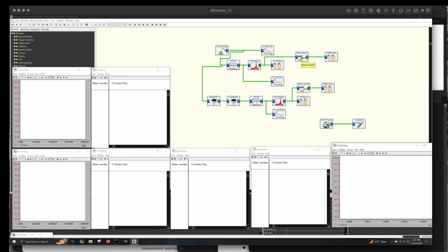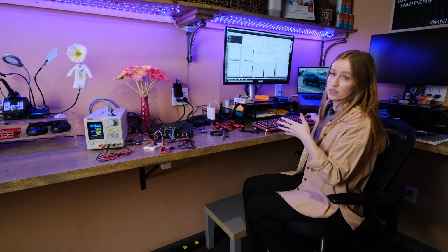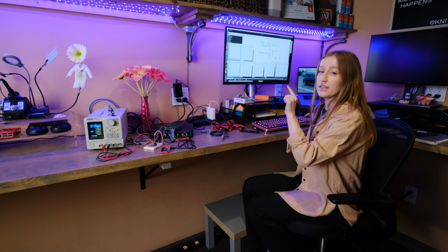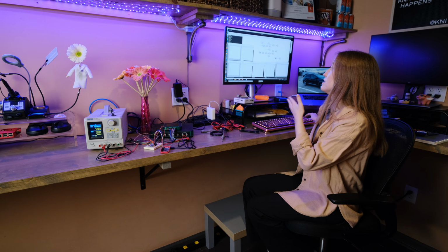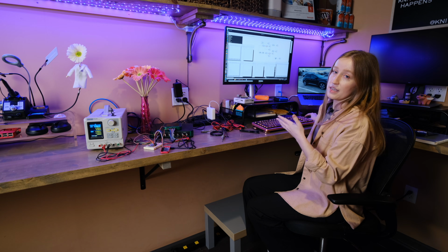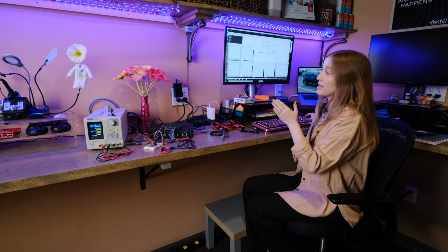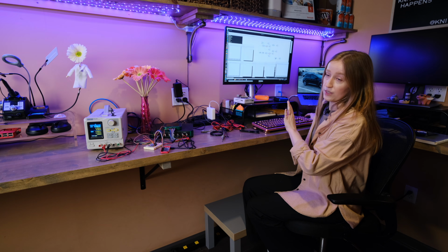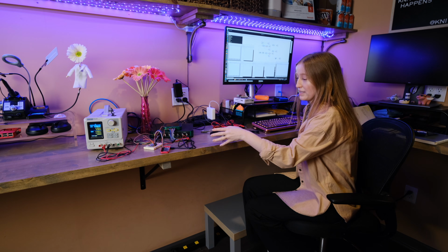That's what this block average is doing: the FFT max operation measures the max amplitude peak it finds and outputs that as a discrete value, which I then put through the block average, which I chose as continuous peak hold. And that's my unfiltered raw input from my DDS.